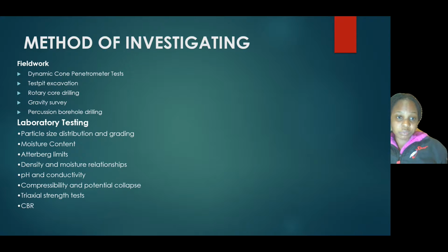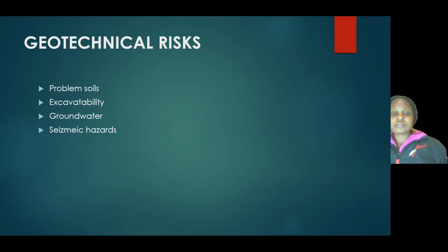On laboratory testing, we consider particle size distribution and grading, moisture content, Atterberg limits, density and moisture relationships, pH and conductivity, compressibility and potential collapse, triaxial strength test, and CBR. On geotechnical risks that are prone on this site, there is problem soils, excavatability, groundwater, seismic hazards.